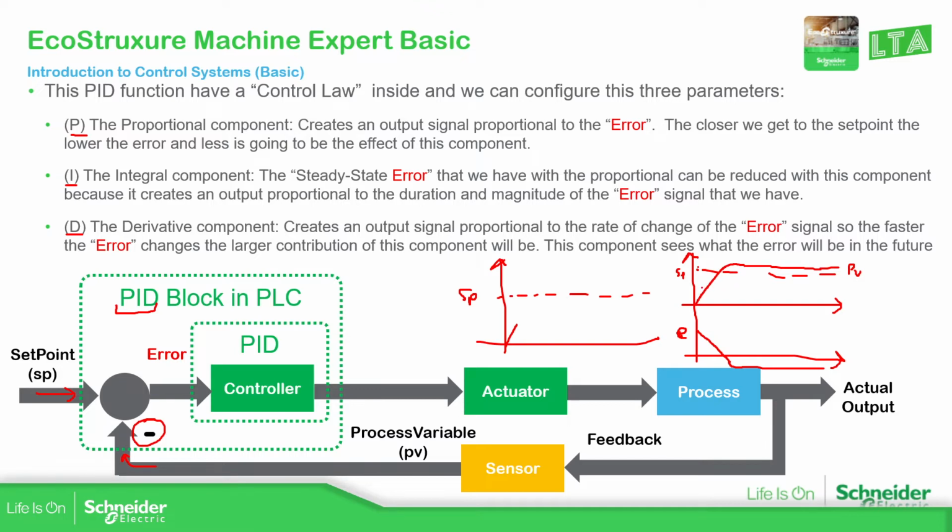Okay, so we have the process value and the set point that we have. This gives us an error. As soon as the error starts reducing, because the error is affected by the proportional part, which sometimes we call KP, the proportional constant, the influence of this combination over time will be less and less, because the error will be decreasing, as you can see over here.